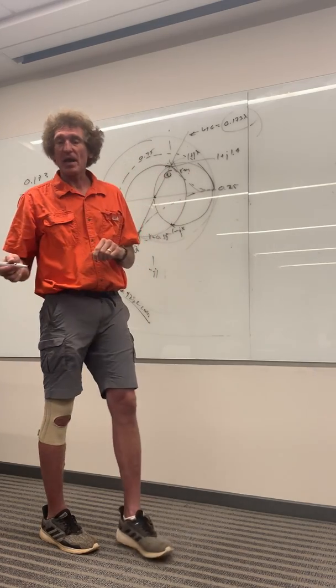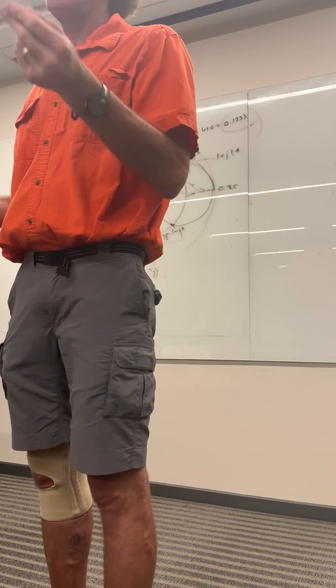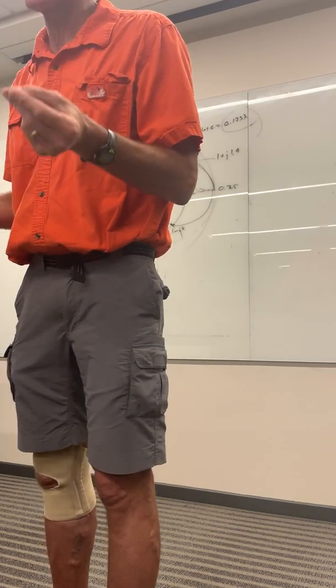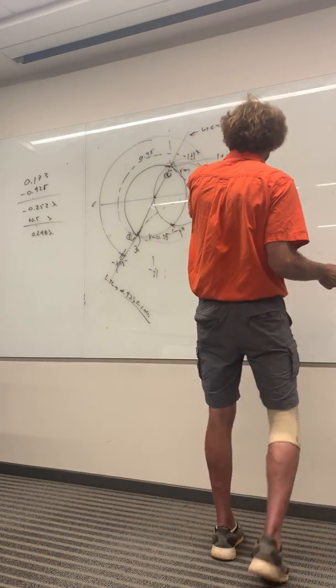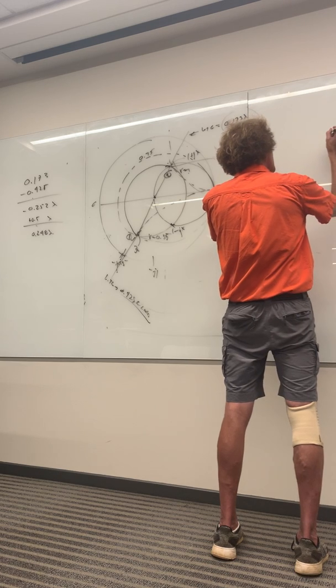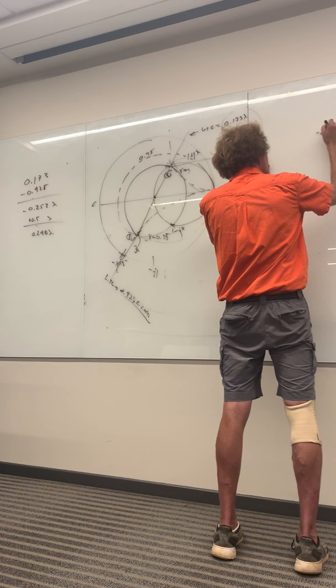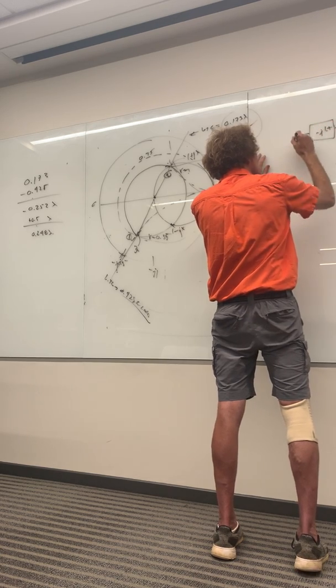If it's plus j, I want to add an element that would have a minus j sense, or a capacitor. Do you agree with me? Capacitive reactance is minus j over omega C. So now I take this value, and I want to add a minus j 1.4 here. That's what I want, right? And that's going to be a capacitor. I want to put that value in line.